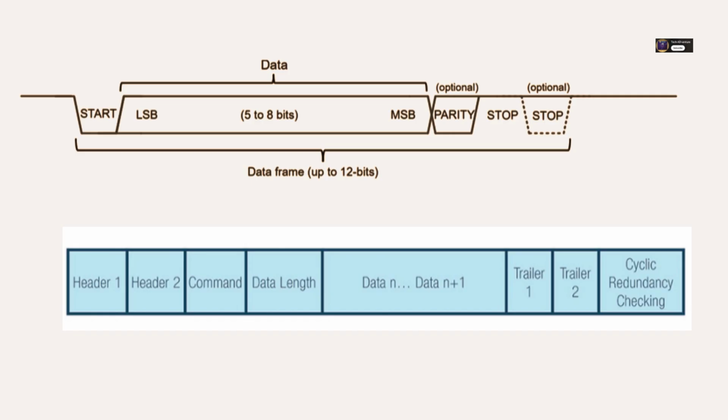Could you walk through designing a super simple custom protocol like that? Absolutely. Let's build on that structure. Say we want to send a command with some data. One, start byte. Let's pick 0xAA. Always start a packet with this. Two, length byte. The next byte tells us how many bytes are in the payload section only.